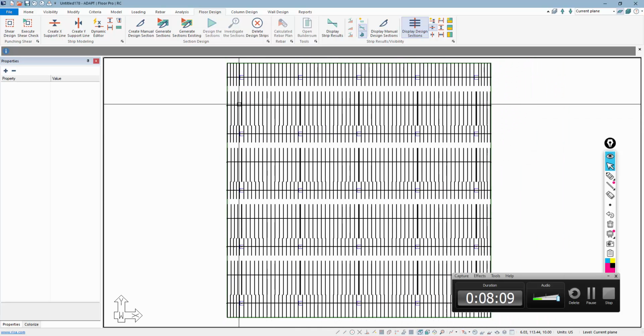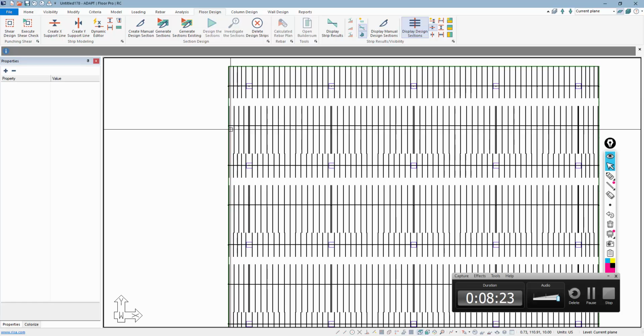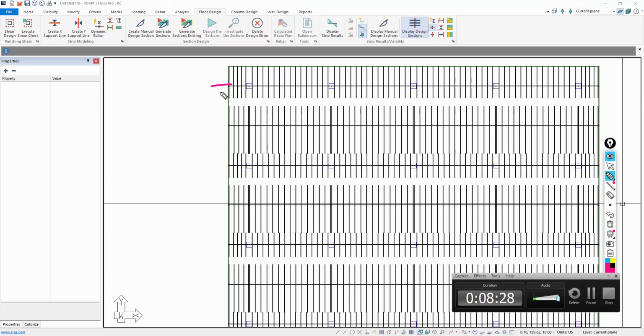Okay, and there is a small little issue here that's being corrected where this gap should actually be filled by the middle strip. So ignore that gap here, here, here, and so on. What we want to focus on is the distance that we're filling in for the tributaries. So the distance from here to here is 15% of this length, which is going to be 4.5 feet. This distance from here to here is 4.5, this is 4.5, and this middle strip basically fills in the balance.